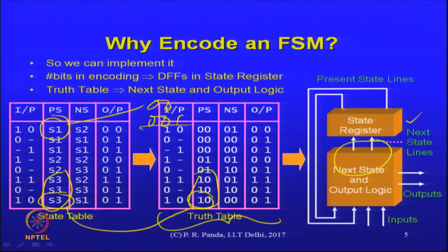And what you see here, these are the Q outputs of the flip flop. Those are fed back into that same combinational logic, and they become the present state. That computation is the next state computation that goes into the D flip flop, preparing the data for the next state. That is the architecture.